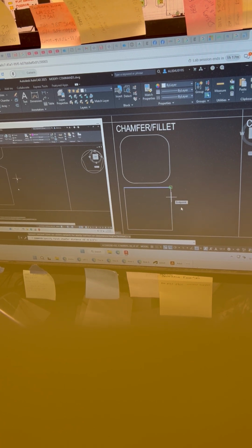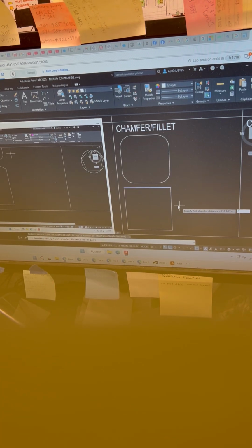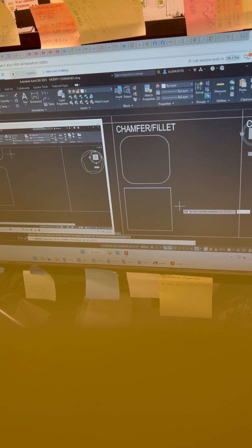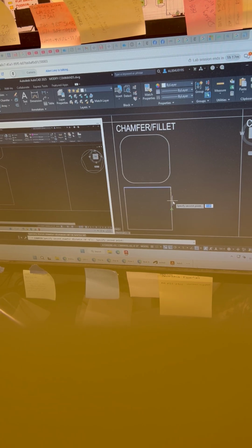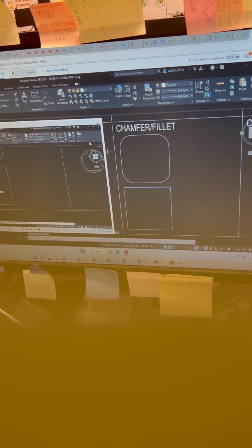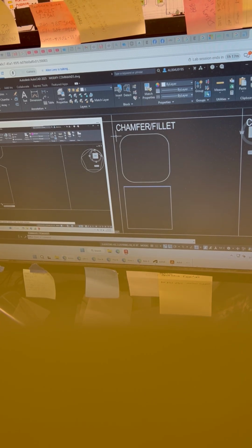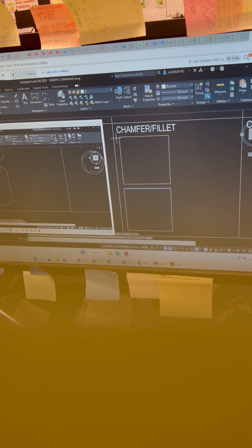All right. Now I want to do a chamfer to all the corners. I forgot to use my multiple. I always do that. All right, so I'm going to start the command again. Now, once you enter in some distances, you don't need to re-enter them. So the first one is going to be the 12-inch, and the second is going to be the 6-inch.